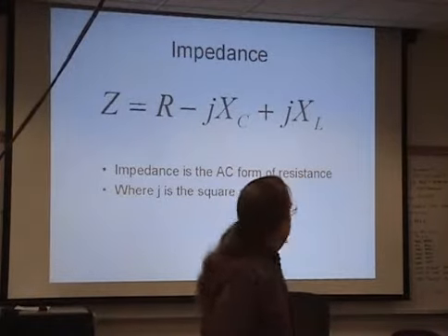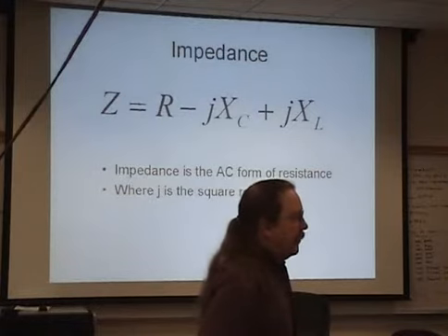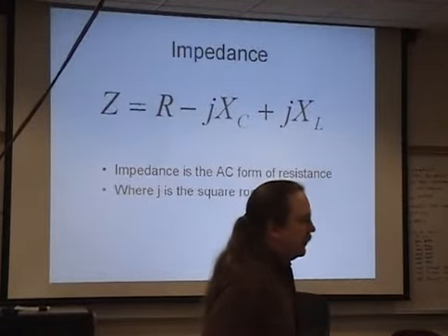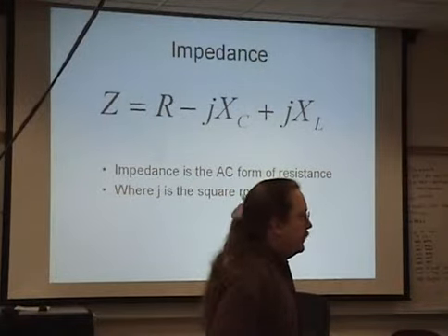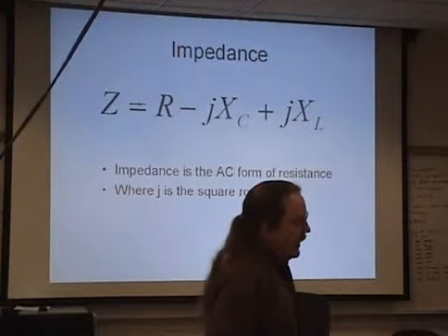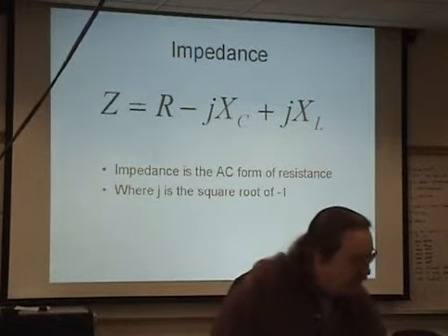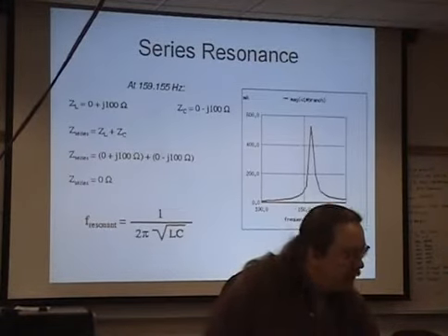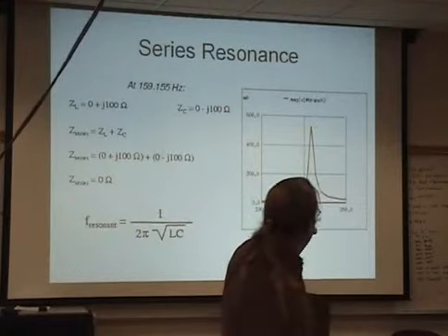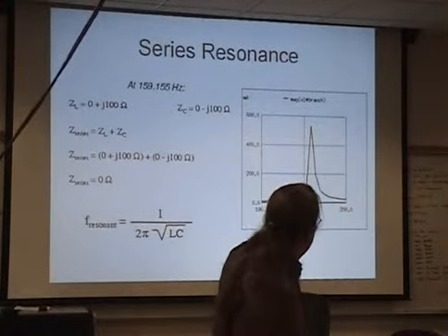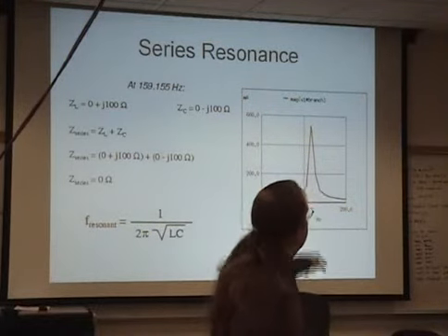So this is a form of a model of an antenna system. The AC output, or RF output, of your transmitter goes into your antenna, and you have some capacitance and some inductance. You always do in any circuit. If you tune that out, then you get to the resonance. So what they did was, I took that equation, I took that circuit, and I figured out the whole thing and went down through the resonance, and we came up with this curve as we swept across the frequencies.